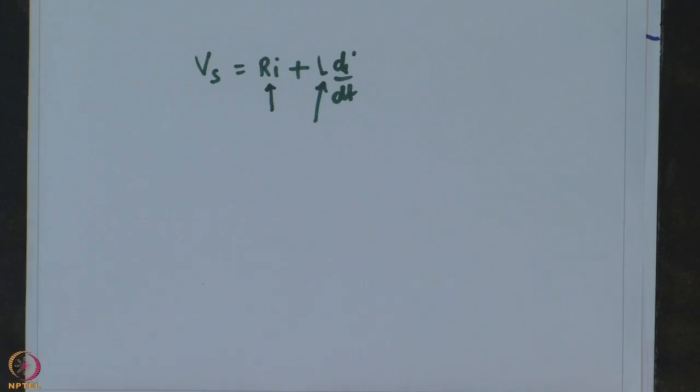We also observe that the circuit steady state analysis using the basic concepts does not lead to a correct solution for all values of t after the switch has been closed. It is expected that some correction factor is required to be added to the steady state solution to get the complete response, which will be valid for all values of t after the switch has been closed.